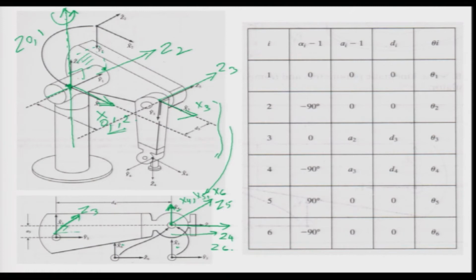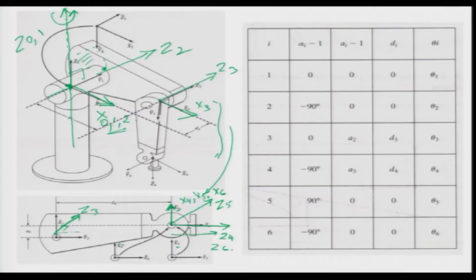looking at the correspondence of the PUMA robot to that of the human arm, I will just explain with respect to the human arm, because it has the same structure. So essentially the human arm has a waist axis which is here, then this is our waist, this is our shoulder, this is our elbow, and roll pitch yaw is here. Now, there is a difference between the human arm and this robot arm. So, in this robot arm, the 3 axes are intersecting.